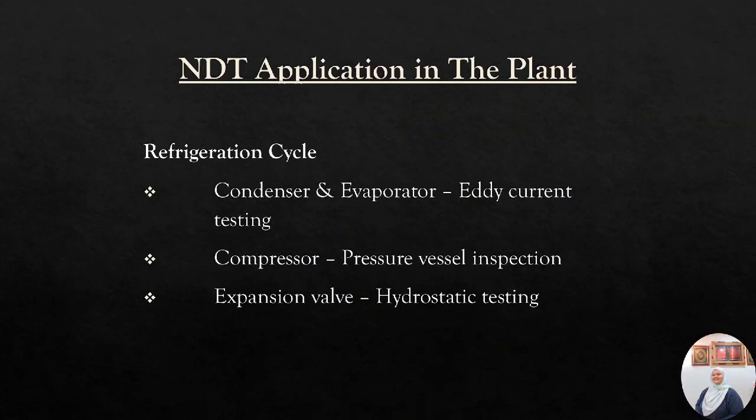The condenser and evaporator will undergo eddy current testing, which is particularly well suited for detecting surface cracks, but can also be used to make electrical conductivity and coating thickness measurements. A small probe is scanned over the part surface in an attempt to detect a crack.